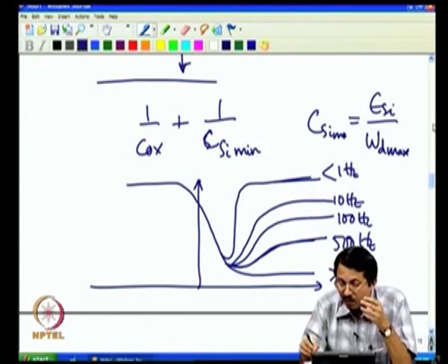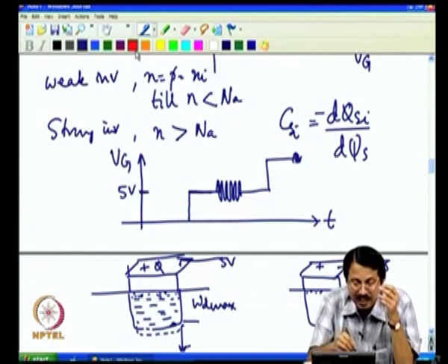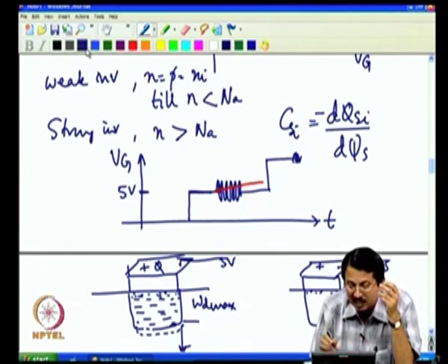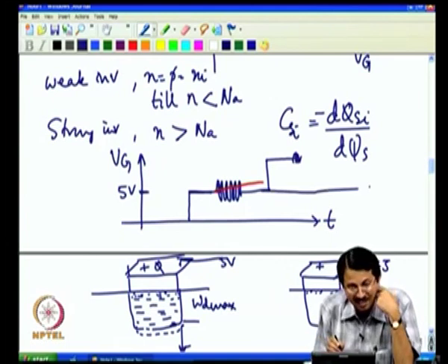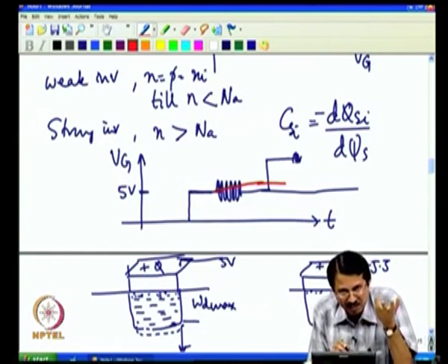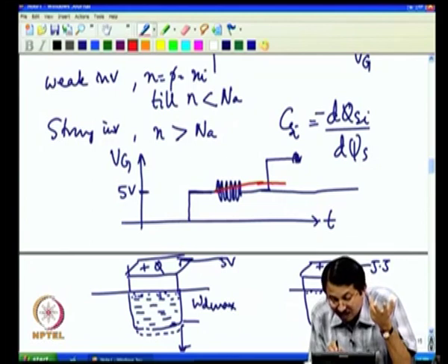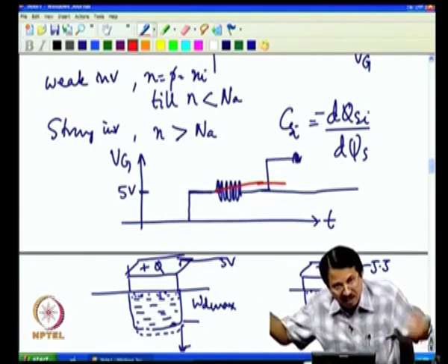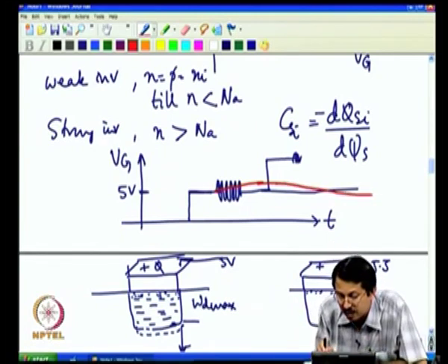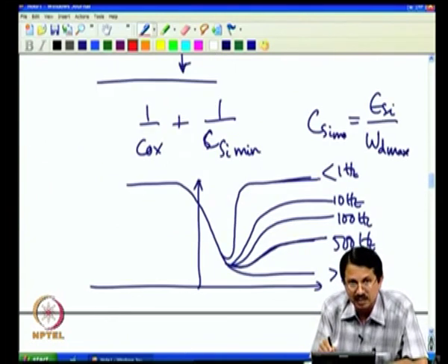Because now just to contrast this here again, what is low frequency? The low frequency is that it is varying so slowly, I am still at the same step, you see, I have not changed the step because I have still not completed my measurement, my frequency is very low, and since going from this voltage to this voltage, typically the AC signal is of the order of 20 millivolt, 30 millivolt of that time, that range. Because this voltage is changing so slowly, I am giving enough time at any given voltage for these electrons to respond, right, and hence you are at this extreme, okay.